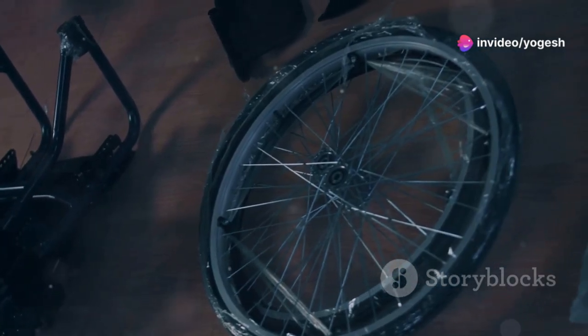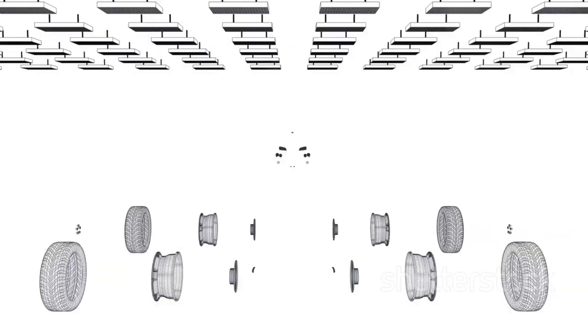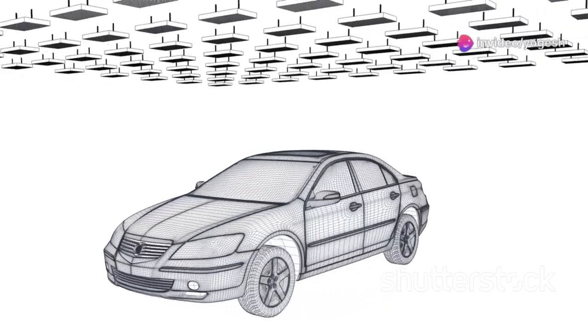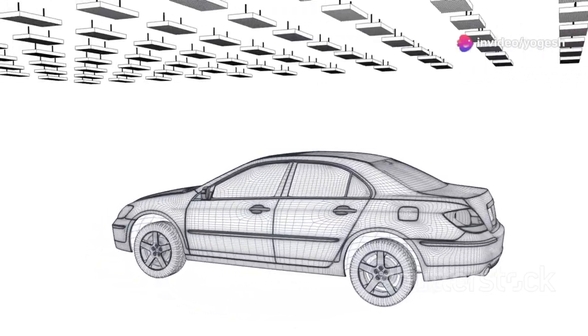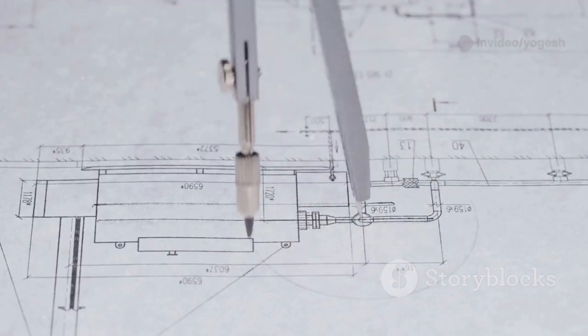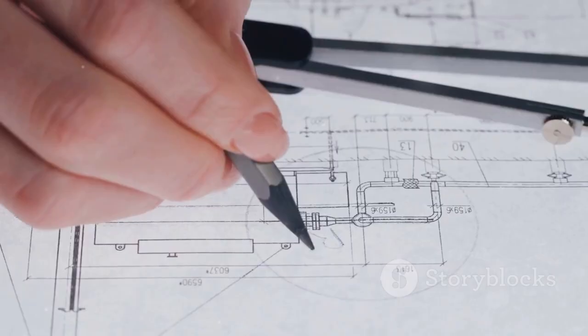The aligned section is used for angled features, such as spokes, bolt patterns, or holes that are not parallel to the main axis. It rotates these features into the plane of the section, making them appear as if they are straight, so you can see their true shape and size. This technique ensures that the feature is shown at its actual size and precise location, which is crucial for accurate